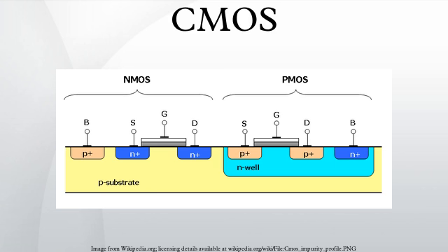Duality. An important characteristic of a CMOS circuit is the duality that exists between its PMOS transistors and NMOS transistors. A CMOS circuit is created to allow a path always to exist from the output to either the power source or ground. To accomplish this, the set of all paths to the voltage source must be the complement of the set of all paths to ground. This can be easily accomplished by defining one in terms of the not of the other.